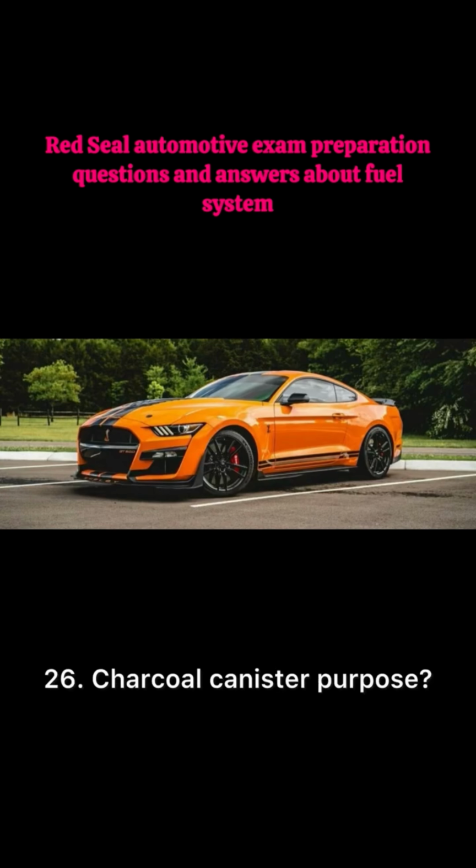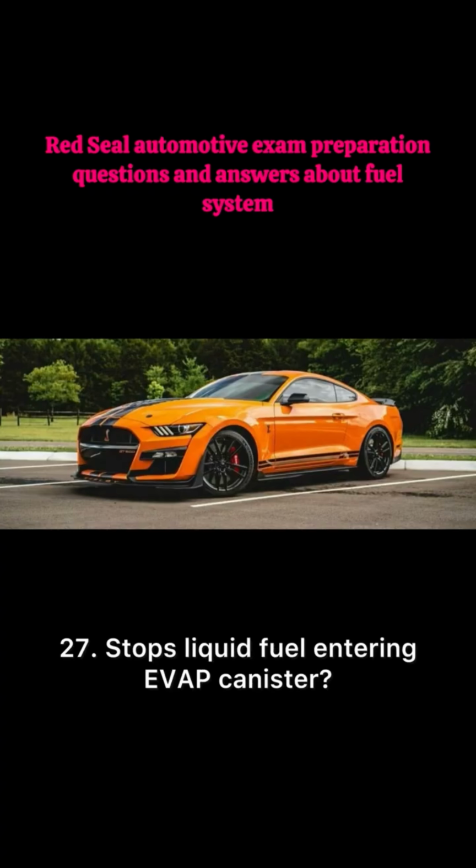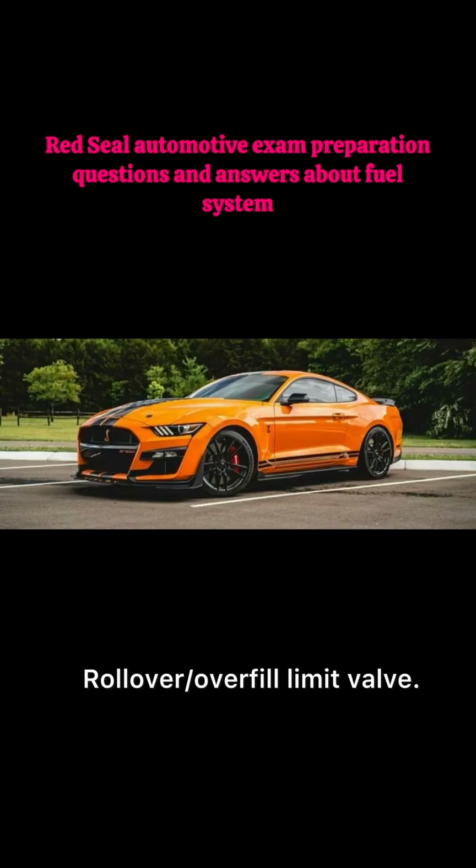26. Charcoal canister purpose. Stores fuel vapors from tank. 27. Stops liquid fuel entering EVAP canister. Rollover overfill limit valve. 28. Stoichiometric ratio for gas. 14.7:1. 29. Leaner than 14.7:1 causes higher NOx emissions. 30. Richer than 14.7:1 causes higher CO and HC.